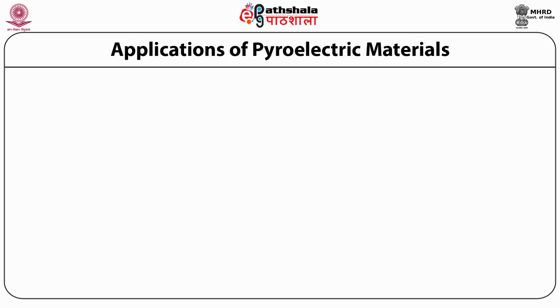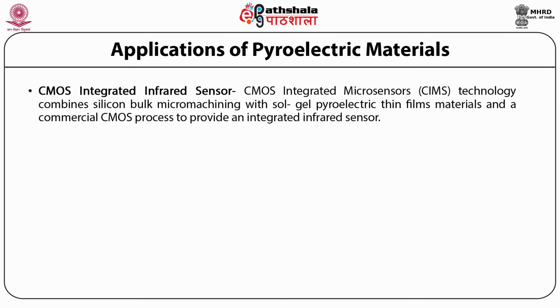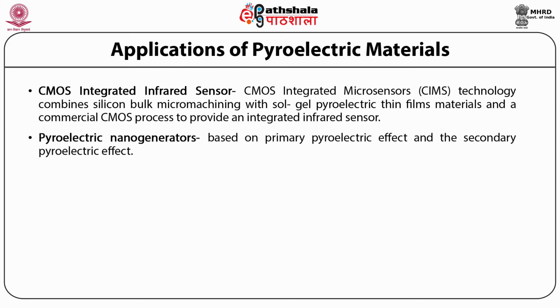Now, let us continue the applications of the PIR sensors. CMOS integrated infrared sensor: CMOS integrated microsensors, SIMS technology combines the silicon bulk micromachining with Sol-Gel pyroelectric thin film materials and a commercial CMOS process to provide an integrated infrared sensor. Next are the pyroelectric